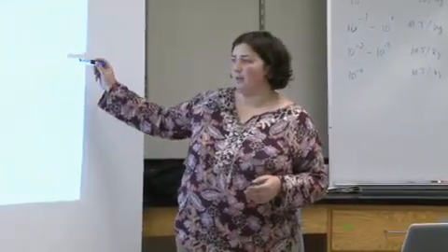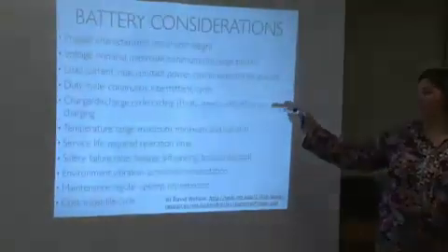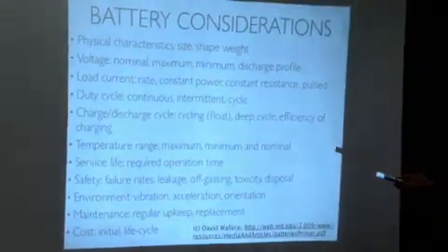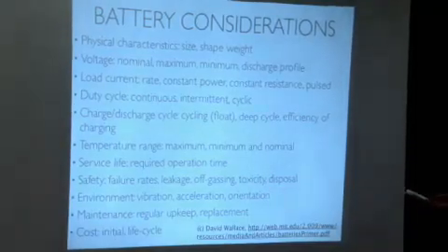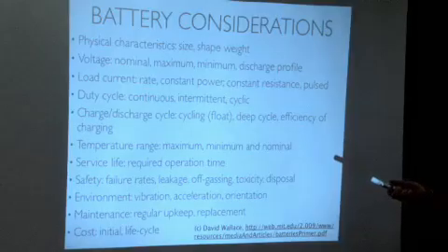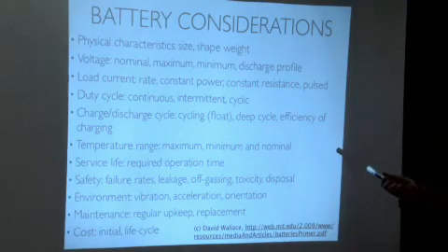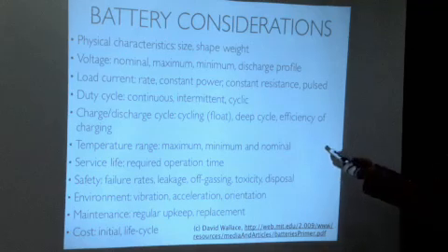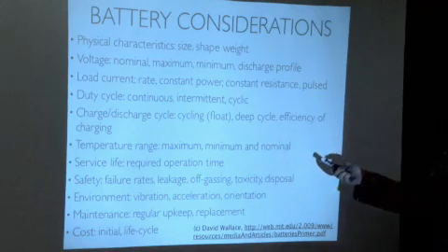So again, as we're talking about the duty cycling, the charging, and the discharge cycling, temperature is another thing. We're generally working in climates that are really hot, and batteries are ideally used in a pretty warm environment, but not 100 degrees. And so they don't always work well. It's 100 degrees F in places we're working, and so you have to account for that.